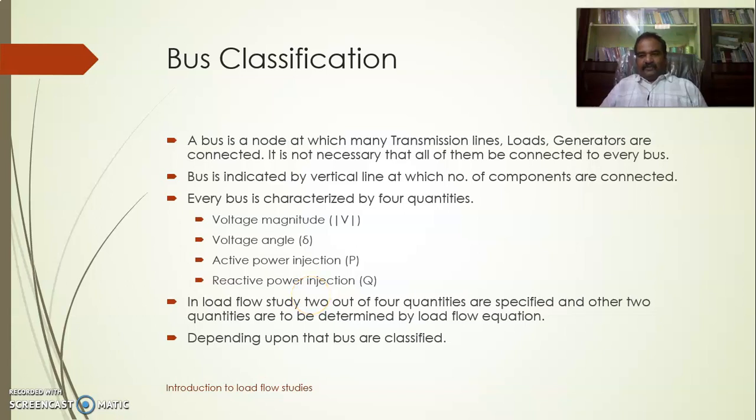So the main point is the concept of bus. So what actually is a bus in a power system? As you have seen in your electrical circuits course, the points in the electrical circuits where there is an interconnection, or a point where two or more elements are connected, is called a node. In the same way, in the power system, technically a node is called a bus. So a bus is just a node at which two or more elements of the power system are connected.